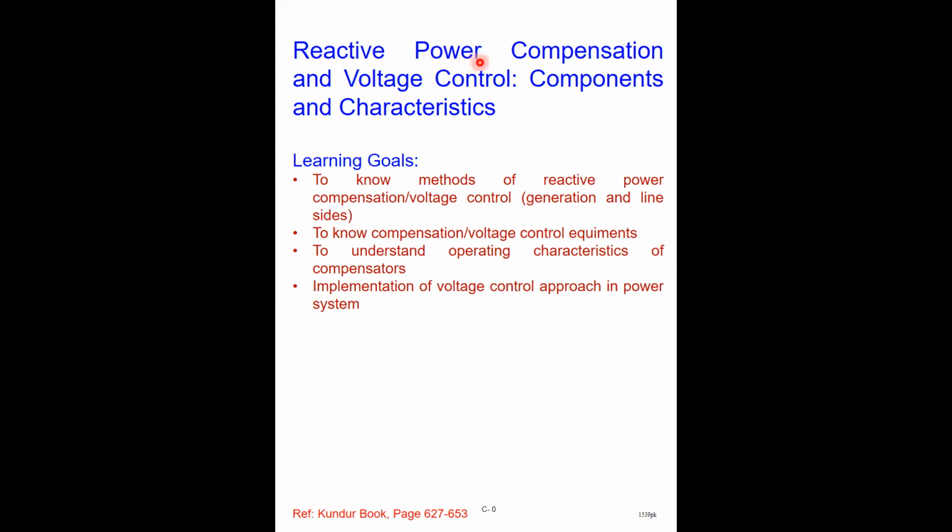So in the system, again in a similar way, we need to have a balance for reactive power and thereby achieve the voltage control. But there is a little bit of difference, because when you talk in the perspective of active power and frequency control, the source of active power is only your generator coupled with the turbine.